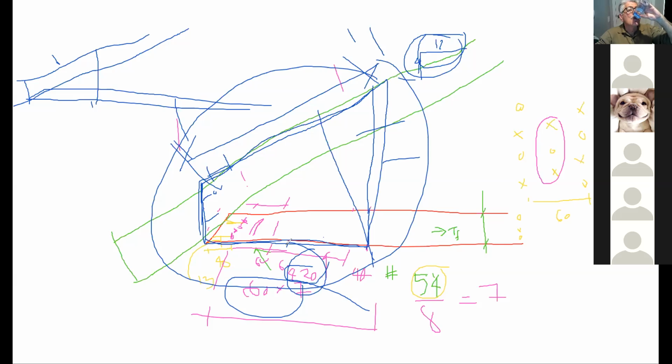Okay, perfect. Thank you, Sid. So you were trying to break your head on how to stick the nails in here. Is that what your problem was? I honestly don't know what I was doing. Yeah, well, I looked at your drawing. So now you're telling me that you're putting 2x6 top and bottom. I can understand why you were starting with that. I don't want to question that, and I said it's better that we talk instead of me trying to answer by email, because we might be just going back and forth. Fair enough? Would it be that I put a 2x6 as the bottom chord?